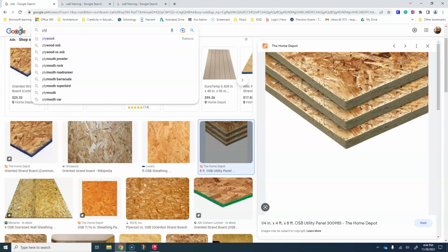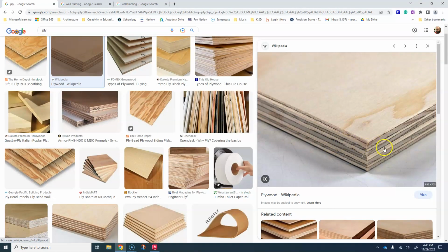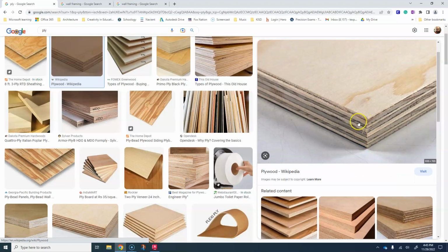Okay, plywood is almost like this. It's actually made almost in the same way, but instead of little pieces of wood, it's actually sheets of wood, probably around 1/16 of an inch or so, of plies, different plies. Each layer is considered a ply. And you can also see that some of those layers are not all the same width. But whatever it is, they're trying to make a piece of plywood that meets a certain specification as far as width is concerned. You can see the different layers in there that are placed together, one on top of the other, and then pressed with glue under immense pressure and heat to make plywood.